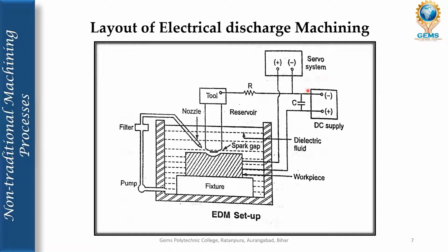Let's see the layout of electrical discharge machining. This is the tank, and this is the fixture which holds the workpiece, and this is a small pump, which is used to pump the dielectric fluid from the tank, and again to flush the dielectric fluid in between the tool and the workpiece.